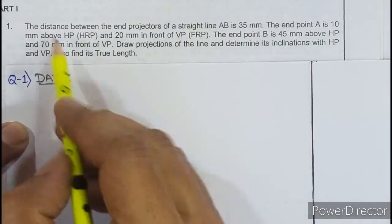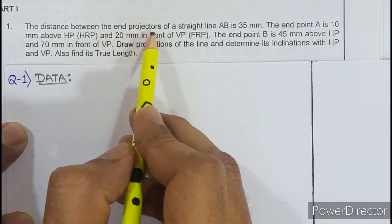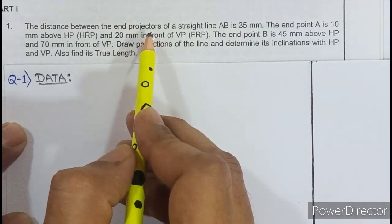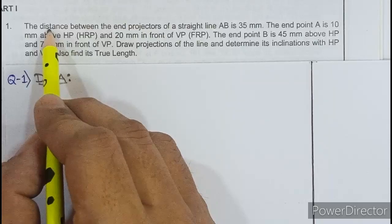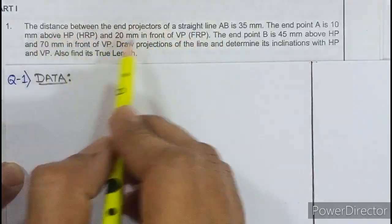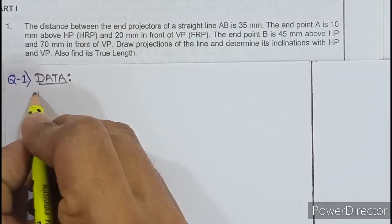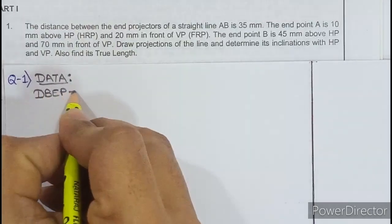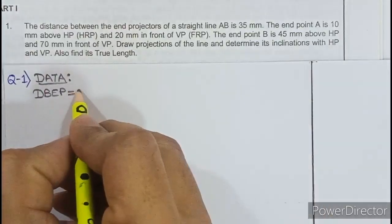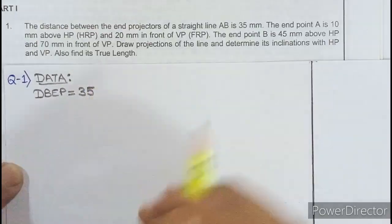So let us start reading the question. The distance between the end projectors of a straight line AB is 35. So they have clearly said there is a line AB and the distance between their projectors is 35. So our first data, what you should write is dBp. So you should write in capitals and then write equal to, and you should write 35. No need to write the units millimeter because entire engineering graphics is in millimeter.